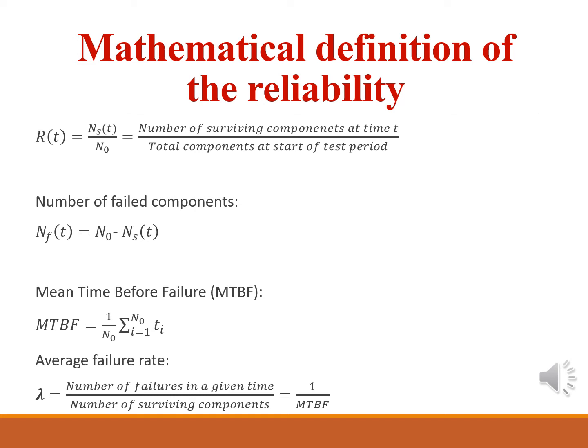The initial period of reduced reliability can be eliminated by a burn-in period before a component is installed in the satellite. So components are tested before they are installed in the satellite, and the initial burn-in period can be eliminated.